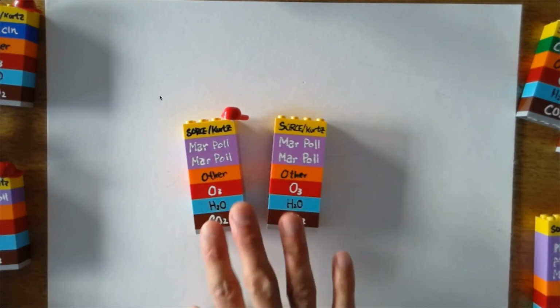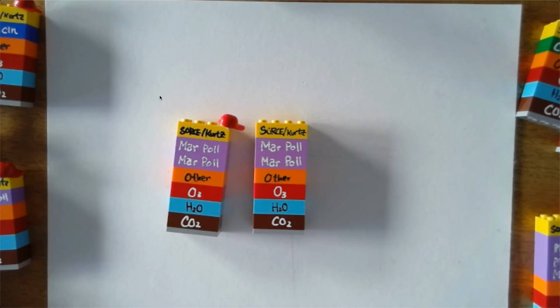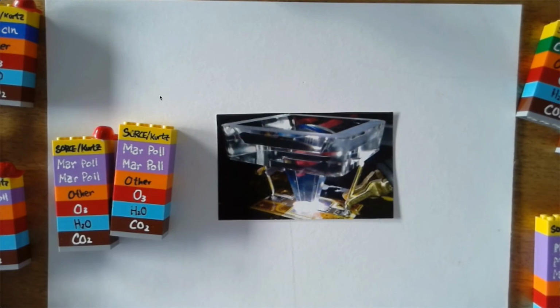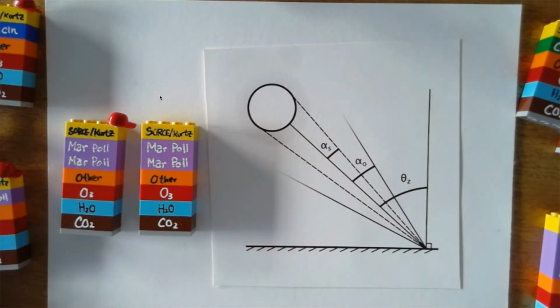But there's one more thing that we haven't considered, and I'm glad that Alex's talk just now was talking about dust and showed a picture with the sun obscured by the dust, and what that is showing is actually circumsolar radiation. Just to go back to earlier in the talk, these multi-junction cells are typically topped with a concentrated system, and these things have very narrow optical tolerances, right? So this is a picture of what it looks like. The implication is that, besides the direct beam coming directly from the sun, it also takes in radiation from the circumsolar region, right?